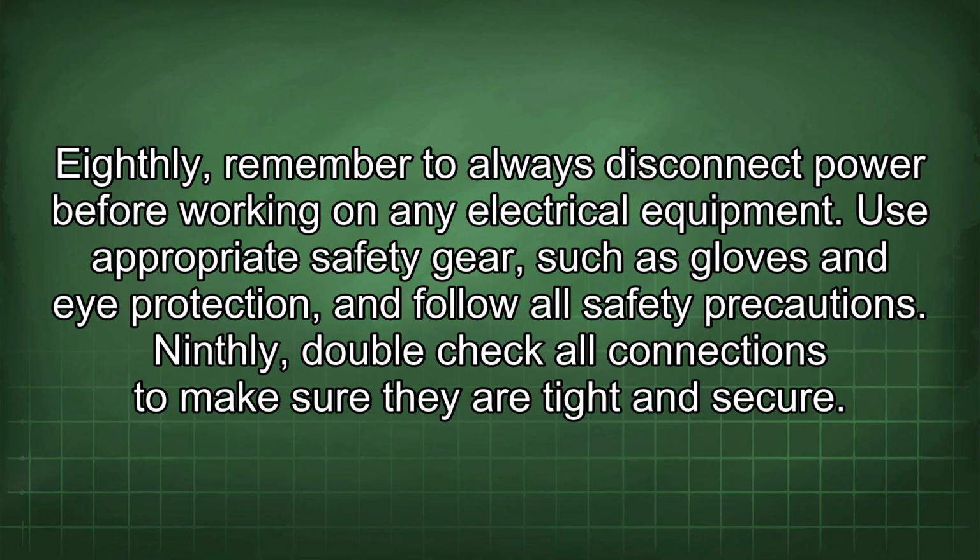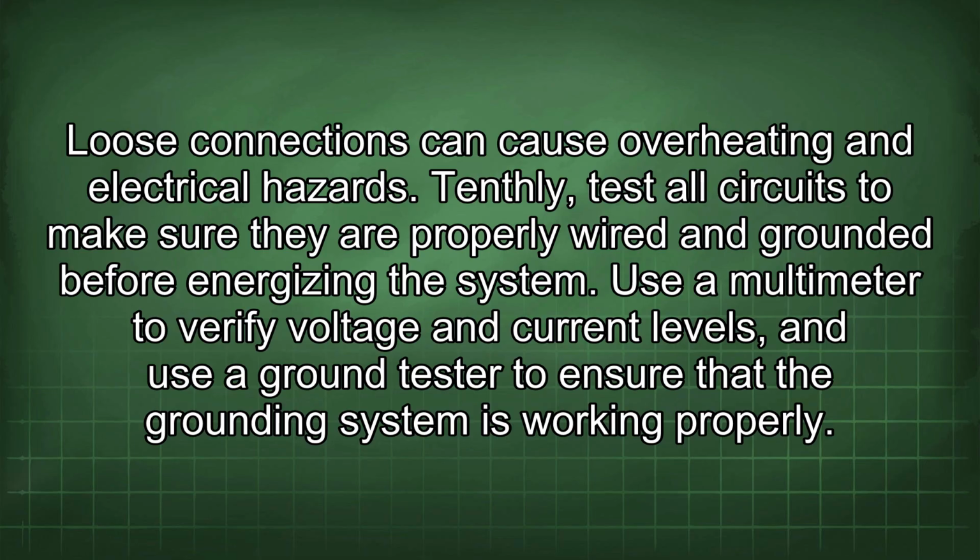Eighthly, remember to always disconnect power before working on any electrical equipment. Use appropriate safety gear such as gloves and eye protection, and follow all safety precautions. Ninthly, double-check all connections to make sure they are tight and secure. Loose connections can cause overheating and electrical hazards.